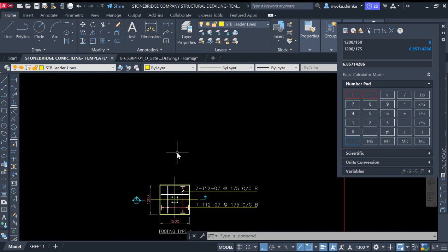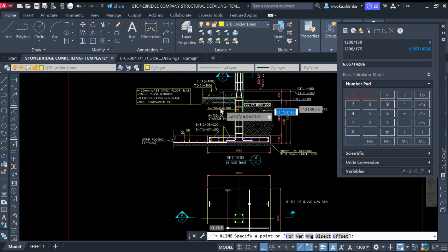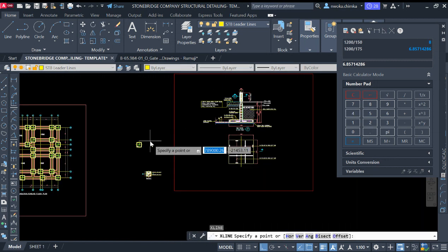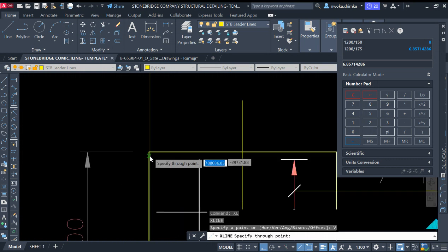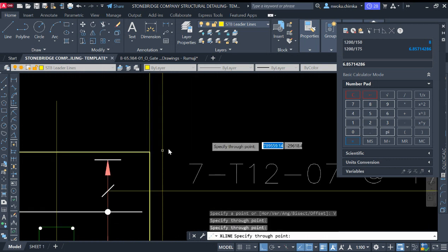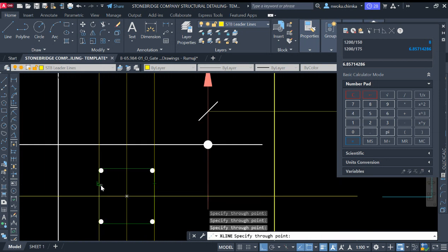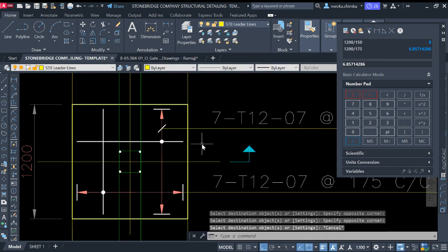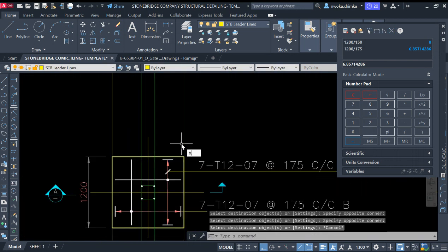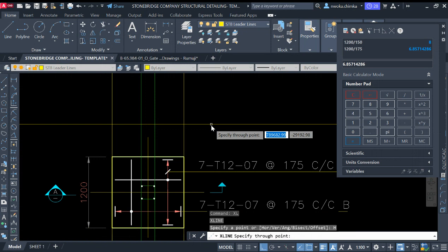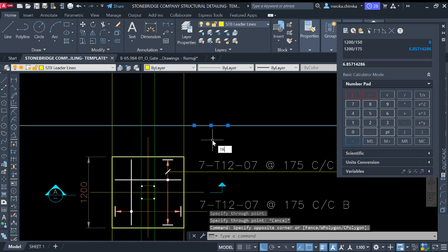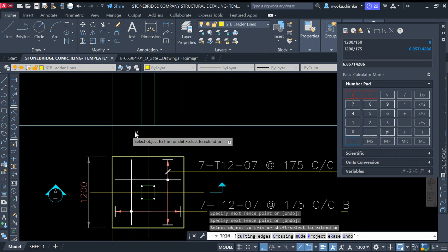Okay, so right now we'll click on what? XL, enter. So we are applying this to draw this. So click XL, enter, V, enter, and put a line here, and then also trace this one out, and trace this column line out also, and also trace this out at this point. Now we will have to change this color immediately because this is a column line. So match this and match this and match this, and then XL, horizontal, to show our base. Click on this, and then we do TR, trim, and then trim off this place and here.